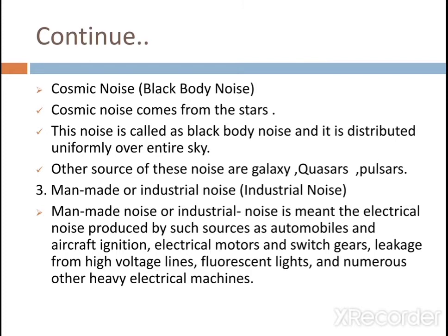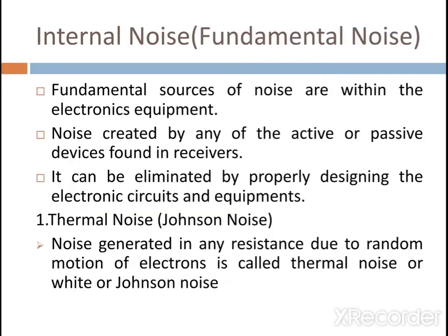So man-made noise or industrial noise is the electrical noise produced by sources like automobile and aircraft ignition, electrical motors, switch gears, then leakage from high voltage line, fluorescent light, then heavy electrical machine. These are the sources that produce man-made or industrial noise.